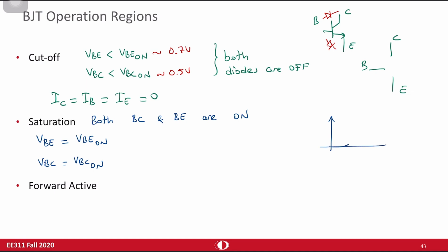If this is the on voltage, let's say 0.7 volts, this is ID versus VD. If your current level is a bit large, then you're operating somewhere in here, and assuming 0.7 volts as the voltage across a diode is not realistic anymore.